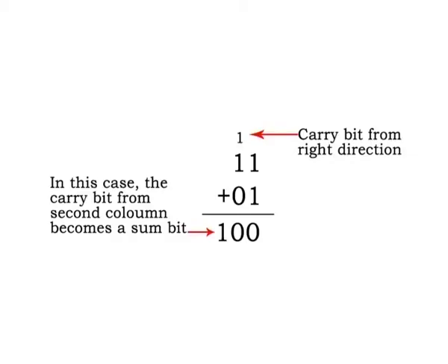Parallel binary adders. Two or more full adders are connected to form parallel binary adders. In this section, we will talk about the basic operation of this type of adder and its associated input and output functions. As you saw earlier and illustrated here, a single full adder is capable of adding two 1-bit numbers and an input carry. To add binary numbers with more than 1 bit, you must use additional full adders.